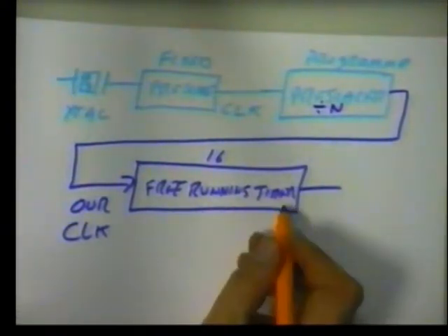All it does is count up. So we've got our clock coming in, a nice low frequency, going into a 16-bit register, and all that does is count. That means we can interrogate that clock anytime we like under program control and read the current time of day. It's very similar to the 8253s we've discussed earlier. You always get that. It's the key.